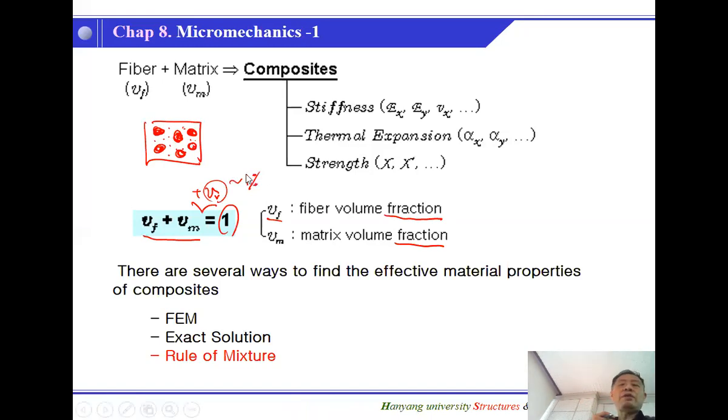Depending on the manufacturing process, such as infusion, we get lower fiber volume fractions, but some advanced processes, such as pre-preg, give us very high volume fractions, such as 70%. But there could always be some void content, which may be important.